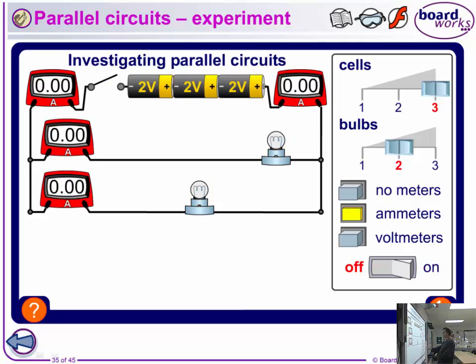If you put some ammeters in there, and we'll try this again, what actually happens when the currents get into here is the charges are splitting and separating into 2 directions. So 1.8 amps as a total is due to 0.9 amps going down this particular pathway and back again, whereas the charges that go down here and come back round here will also produce a 0.9 amp current down here. So the total current has split in 2 directions to give you 0.9 amps down each of those pathways, and you get a larger current.